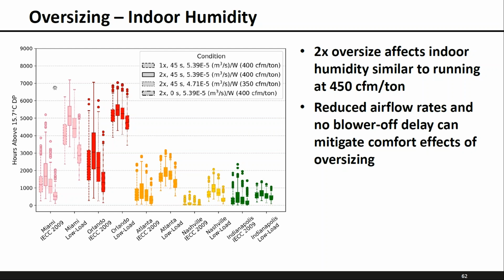But if we want to look at what the actual latent load is, this was best done by controlling the RH so that we could take a delta, so that the indoor humidity ratio is fixed.